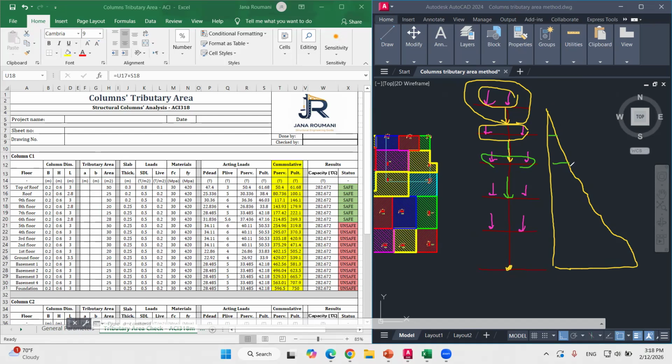So at each floor, the axial load in the column will increase, reaching a maximum at the base. This is what should be seen in the model. If this is not the behavior, there should be something wrong. In the second part of this video, we will do a comparison between this method and the model, to see in firms how this method is used.